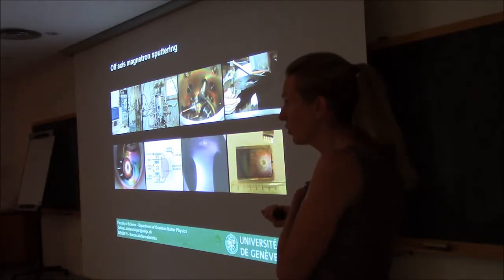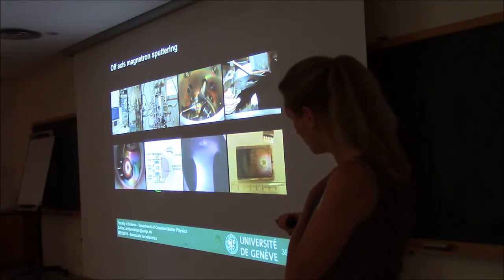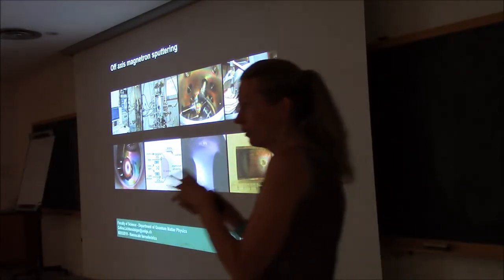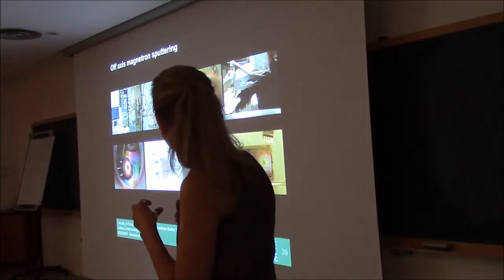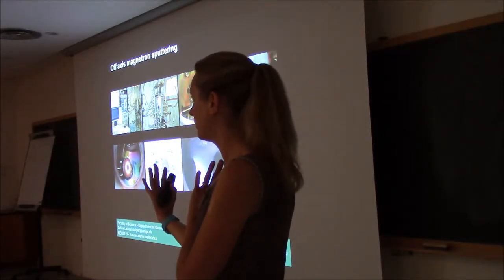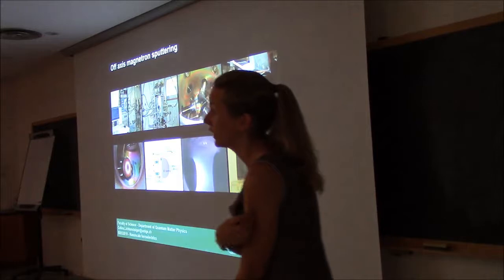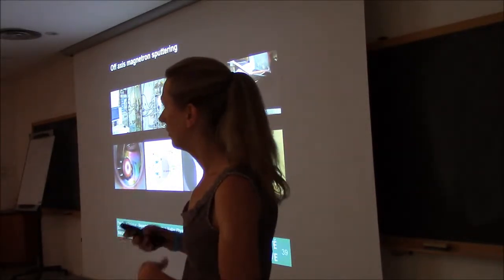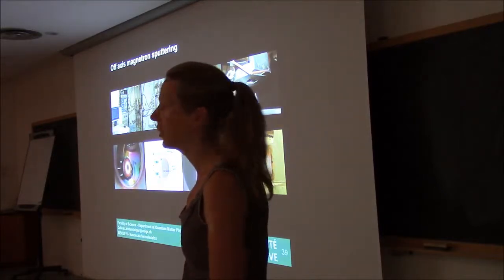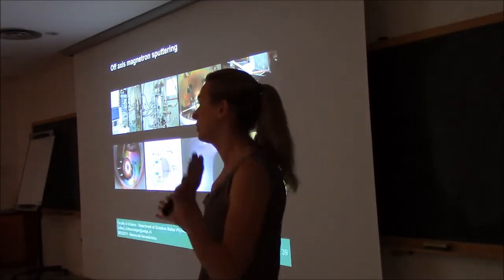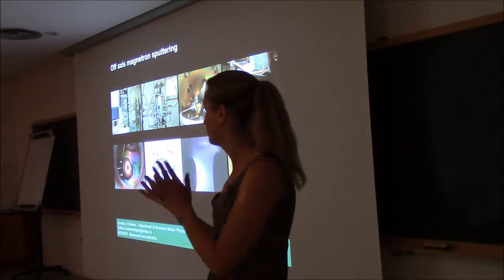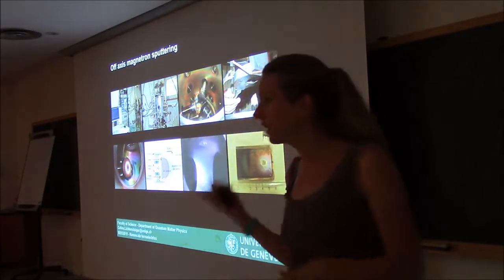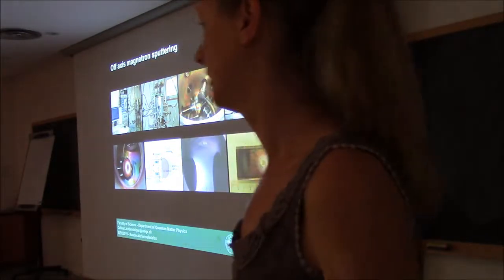And in terms of stoichiometry, we usually work with targets that already have the right or very close to the right stoichiometry that we want. If you go in the direct way, it doesn't work. This is because we are working with oxide materials. If you sputter metals like gold or platinum, you don't care, because you just bombard, and if some species are removed, it doesn't change the stoichiometry. But in oxides, it's very important to be in this off-axis geometry.